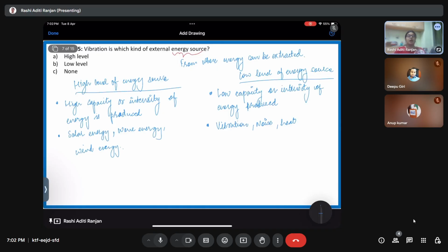Now, I cannot do anything to avoid that vibration. So at least what I can do is use that vibration to produce some energy for some small work. For example, there is a sensor present on the machine or near the machine, and that sensor requires constant power, constant energy. But the energy that it requires is very less. So, what I can do is, as we have learned about the cantilever beam, I'll apply a cantilever beam and then I'll apply a piezoelectric patch. And since the machine will vibrate, the cantilever beam is going to vibrate. At the free end, there's a piezoelectric patch. The piezoelectric patch is going to vibrate. It is going to produce voltage across it. The voltage can be extracted in terms of energy, and that energy could be useful to give energy to the sensor for the working of the sensor.